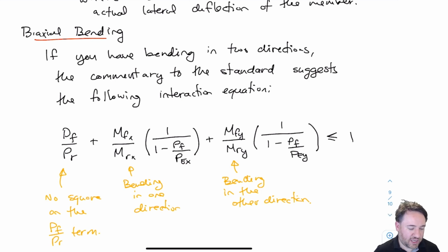So since we have bending in both directions now, it's no longer clear how that difference between compression and tension is going to affect the section, because I could be applying tension from bending in one direction, and then in the same place I'm applying compression from the other. So it's really just the net tension that we're checking against here. So when do I reach that total tension strength, including consideration of amplification for P delta effects.